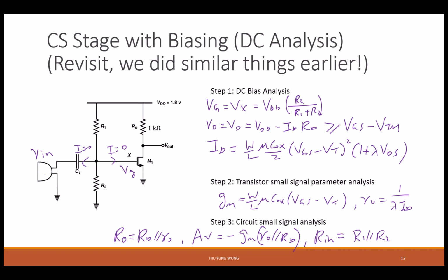But if you look down, what is this circuit? Series. It's just the same as this circuit. So your new RS dash is this whole thing, and then you plug it into that equation again, right? So in principle, it's just looping, like when you're doing programming. Substitute, call the same function, self-call yourself. So you keep expanding the term.